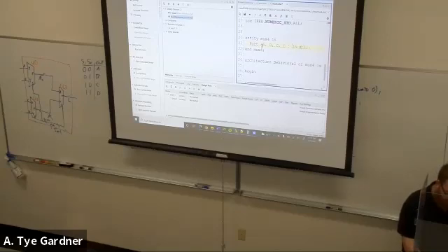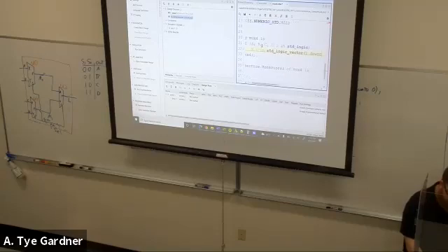They are ins and they are standard logic. I then have S, which is an in, which is a standard logic vector of 1 down to 0. And then I need my out, which we decided to call L, which is an output of standard logic.